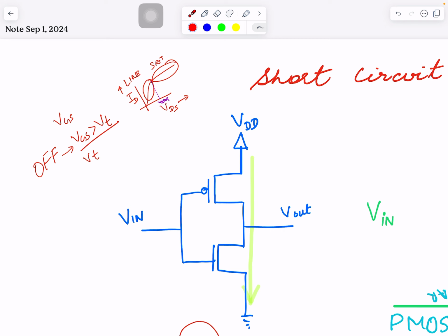So the sequence of operation, the way it happens, even though we explain it as off to linear for NMOS, and I guess the same is for PMOS. Actually, what happens in an inverter is it's off, then goes into saturation. A lot of people, I used to be confused with this one too when I studied these things the very first time. And then it gets into linear. And this is where it settles finally, steady state. So this saturation is what happens during the transition.